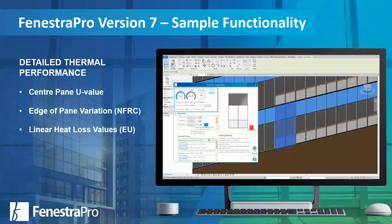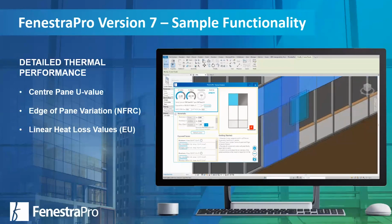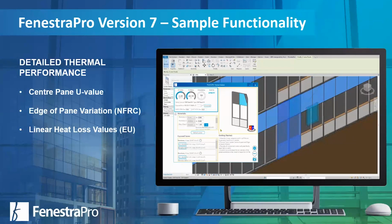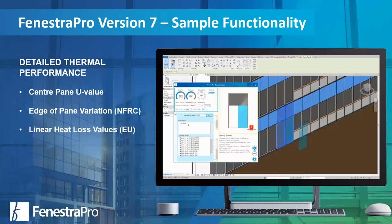In the EU, we look at linear heat loss, or psi values, where the frame meets the glazing, or where the glazing frame meets the wall. So, all those variations are taken into consideration. You apply the various different values for that linear heat loss, or for those edge of panes, the U value for your frame, the U value for the opaque elements, and it gives you that detailed thermal performance calculation with much more detail.